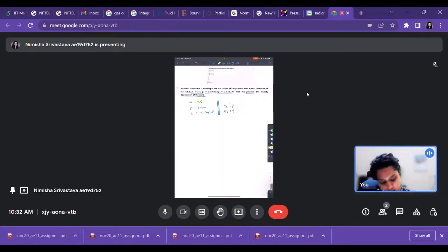So let's see what we already have. We have the Mach number. For a normal shock wave, that is enough for us to know the downstream properties. So we'll look into our gas tables and try to find where this M1 is on the gas tables.